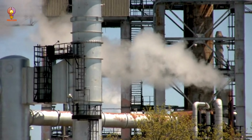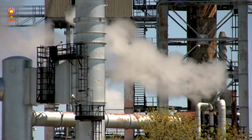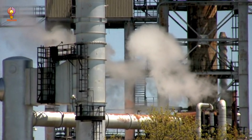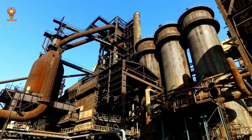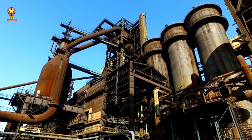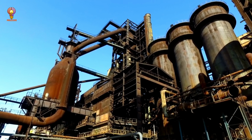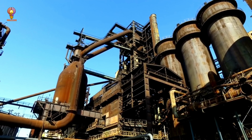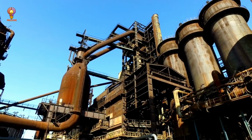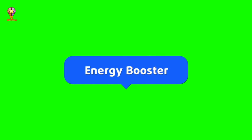Oxygen steelmaking, pure oxygen. Some plants are switching from air to pure oxygen in the steelmaking process. This change improves the efficiency of the process by increasing the reaction temperature, allowing for better impurity removal and faster processing times. Top gas recycling blast furnace. In this variation of the traditional blast furnace, the waste gases produced during the reduction process are recirculated and used to preheat the incoming iron ore or air. This helps recover energy that would otherwise be wasted and reduces the amount of fuel needed.